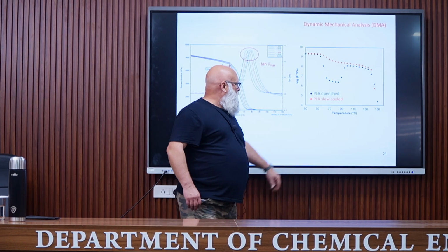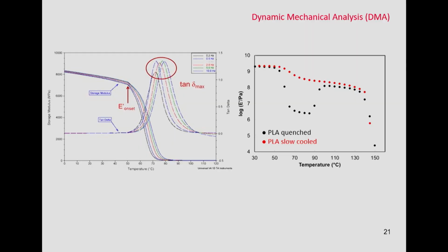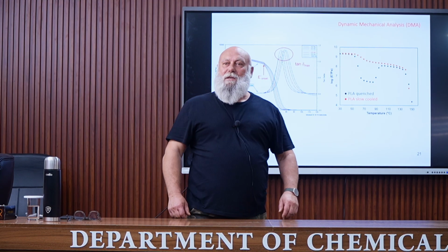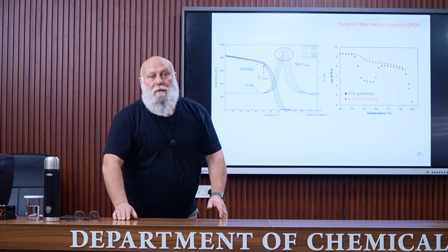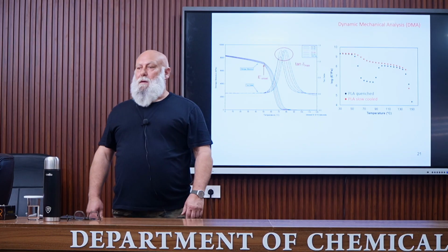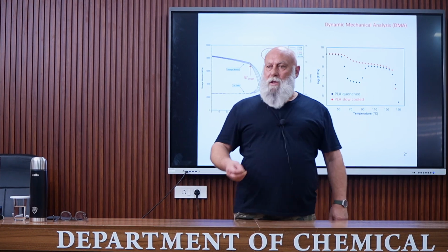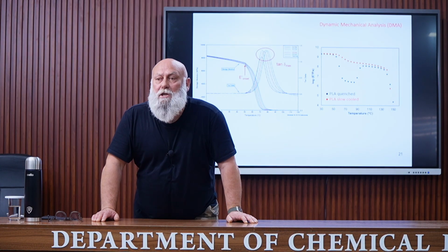So this is something which is very specific. Maybe I can describe it briefly. It is for PLA, polylactic acid. One of the characteristics of PLA is that the kinetics of crystallization is slow. So you know that a semi-crystalline polymer can be obtained as a fully amorphous polymer or low crystallinity polymer by applying what is called a quenching.